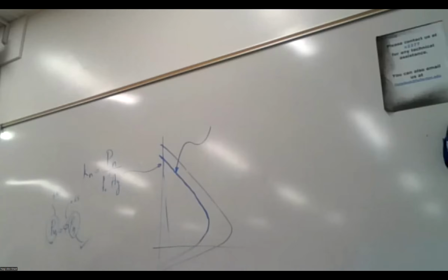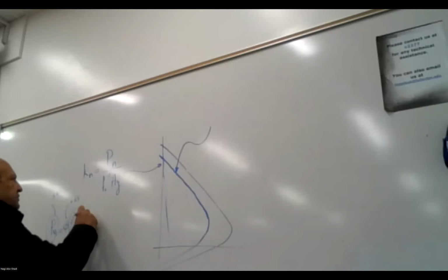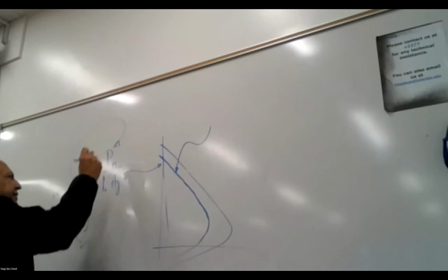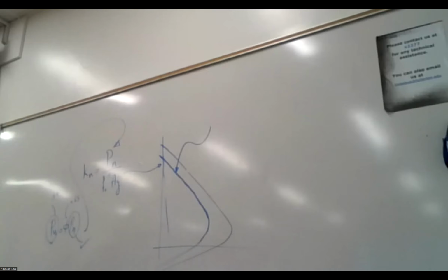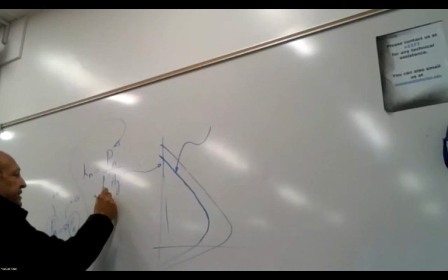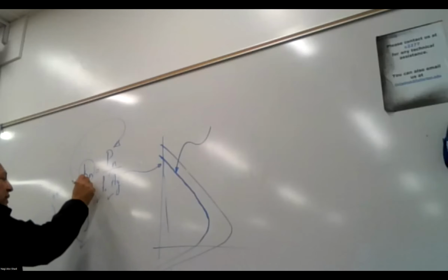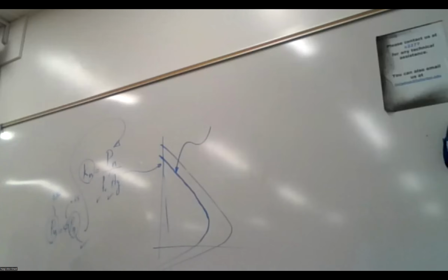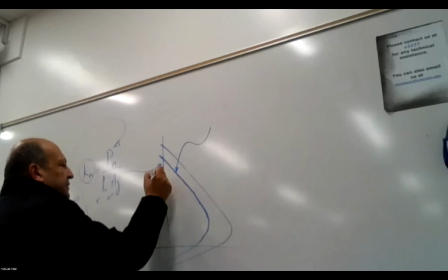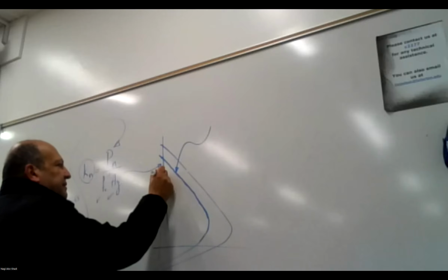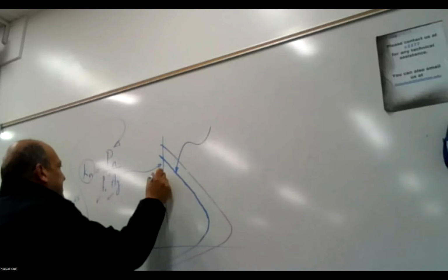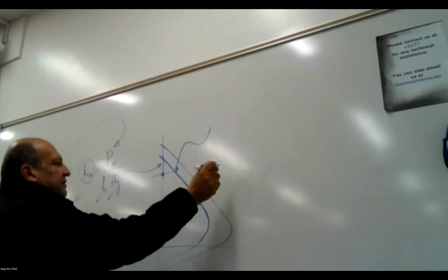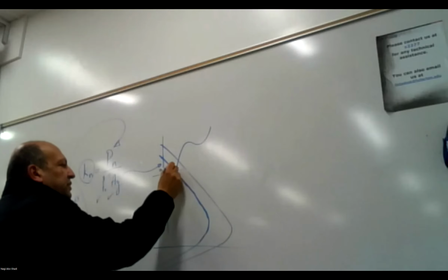Right, good. If I have P sub n, I'm going to take it and use it in this equation. I have f prime c, I have A sub g, therefore I have K sub n for the demand, because this is about the demand. So this is going to be my curve. K sub n, I'll find it. It's going to be about here. You know what? This is going to be my K sub n for the demand. So my demand point is going to be this point.